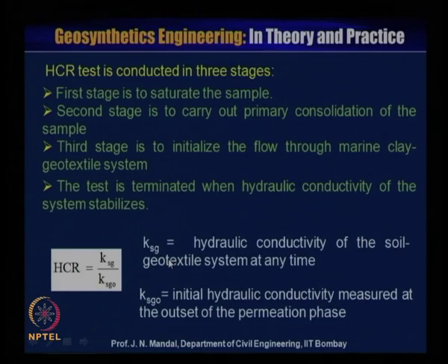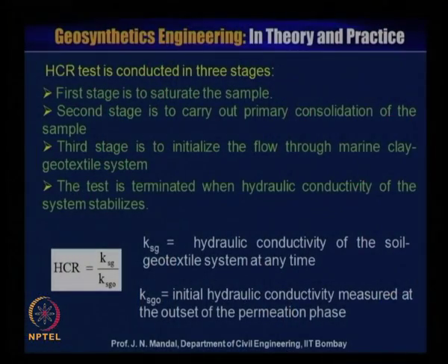So, this HCR test is conducted in 3 stages. First stage is to saturate the soil sample. The second stage is to carry out the primary consolidation of the sample, and third stage is to initialize the flow through the marine clay geotextile system. The test is terminated when the hydraulic conductivity of the system stabilizes.